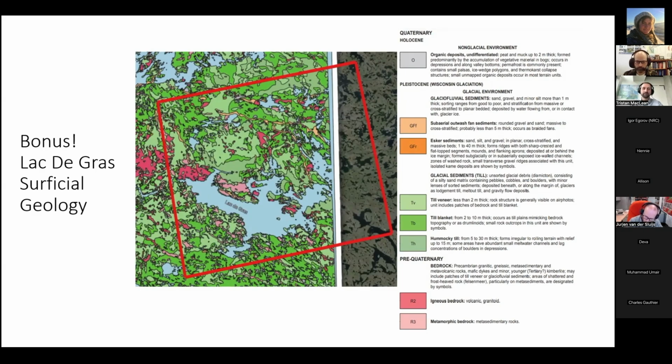Also, it's just the limited scope of the data. With InSAR, you need about 10 years before you can really lock down the trends. So that's the biggest limiting factor, I think, with the InSAR component of this. Does that answer the question?